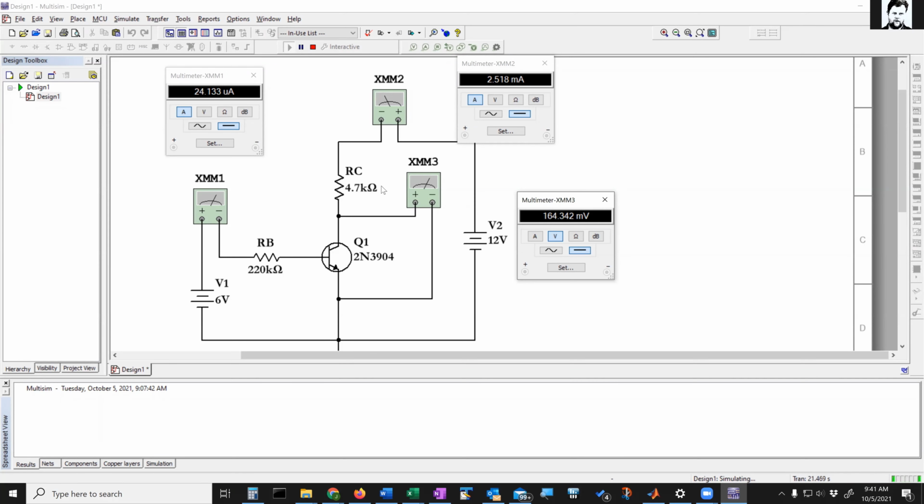So think about this resistor here. This resistor is not getting the full 12 volts, but it's getting pretty close, right? It's getting 11.83 volts. So if this wasn't a resistor and this was instead like a motor or something that you were controlling, let's say you wanted to have a motor up here and you switch it off and on with this transistor, that would be reasonable. That would be acceptable, right? The motor would not be getting the full 12 volts, but it would be getting darn close to it. 11.83 is close enough for most practical purposes here.